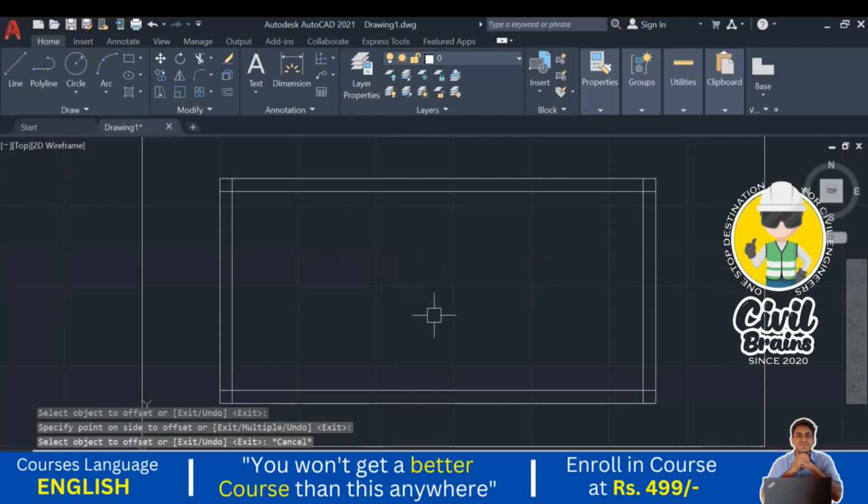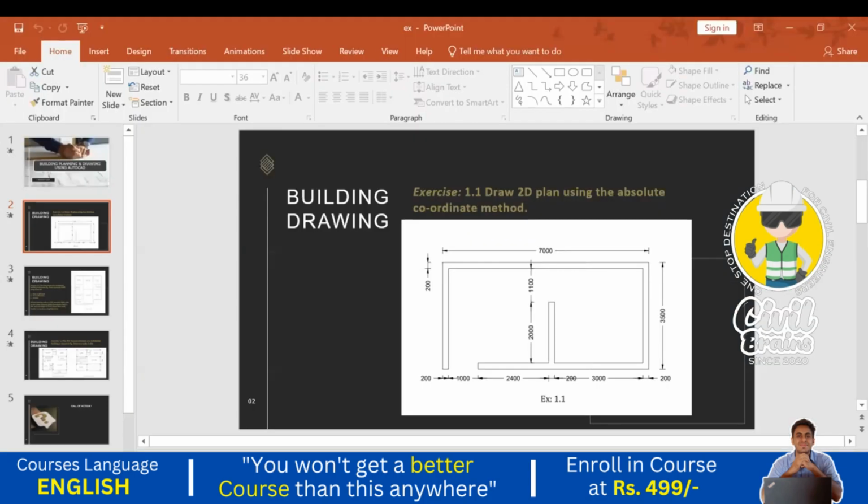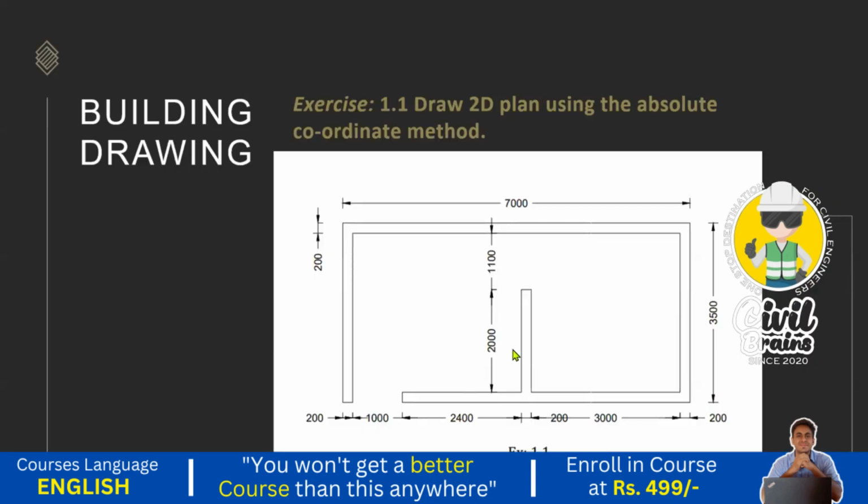Clear? Okay, fine. So what is the next? Next I see there is one partition wall. What is the distance? The partition wall distance is 3000. Here it is mentioned from the outer wall, next 200 is the wall thickness, next 3000 is the inner dimension, next again 200 for the wall, next 2400 till the door level, then 1000, then 200. Okay, I just draw this 3000 wall.